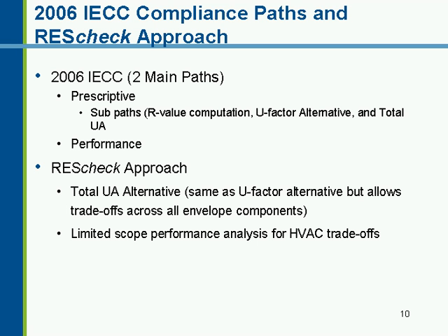And also in the 2006 IECC is performance. This is a simulated performance alternative that's available in the 2006 IECC. It's the other main path. Now, how does REScheck handle these? REScheck hasn't changed. It's still a total UA alternative approach.